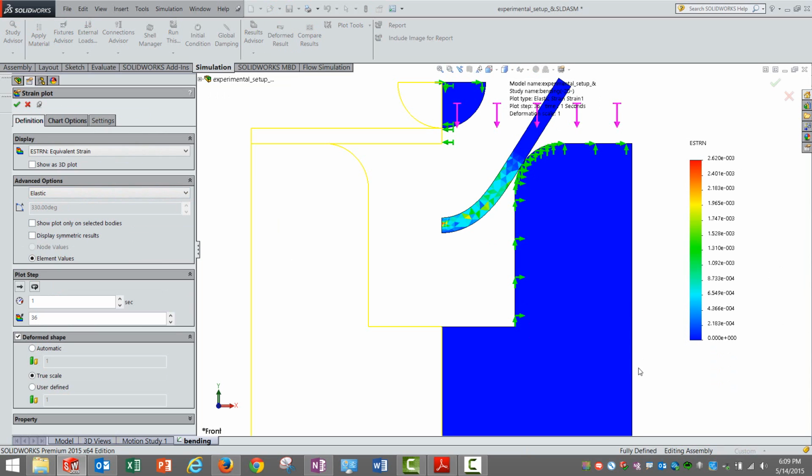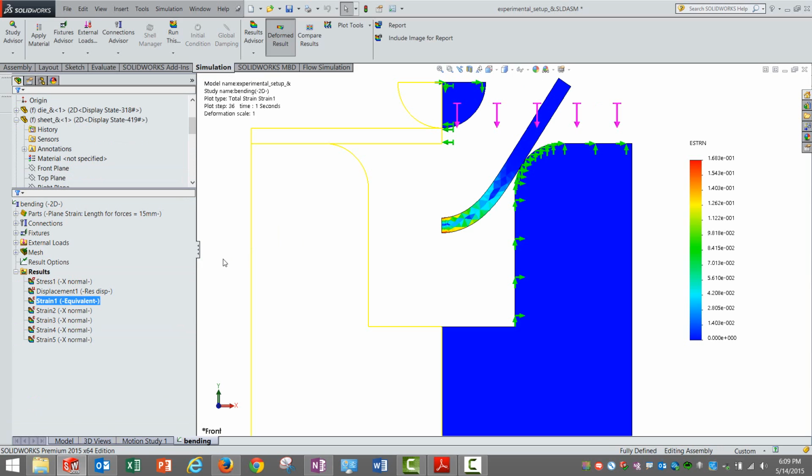This splits the strain into different components, and we can visualize how much plastic, elastic or total strain is present in this body. Obviously punch and die come back to their original location and they're fine, whereas the brass component is going to be subjected to a certain amount of plastic deformation, and that's what we are studying here.